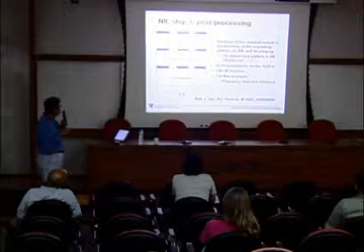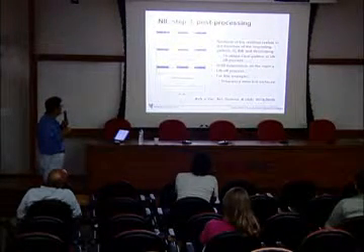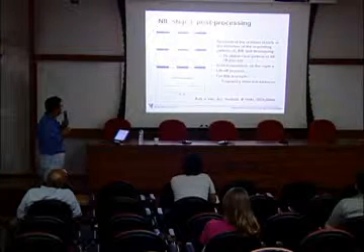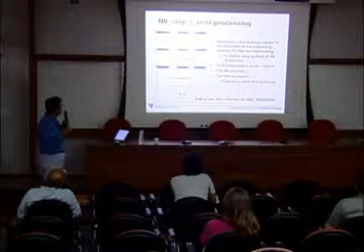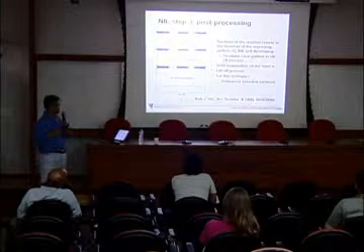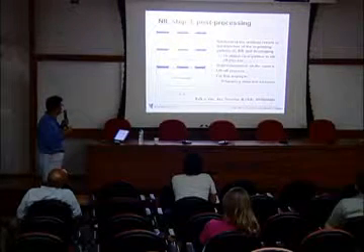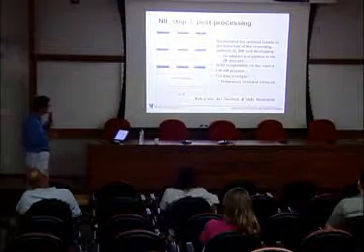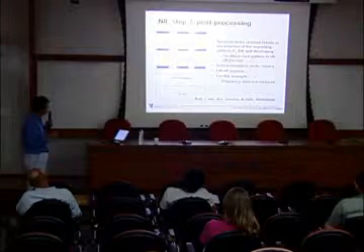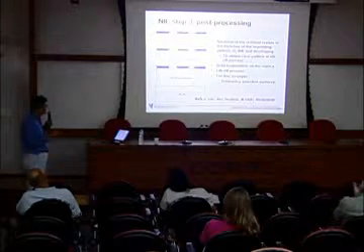So we have 2 layers of polymer, and then with the pressure and heating, those materials will be moved, transported. Then we have some of the debris out there. With the oxygen plasma, we can clean up the surface, and then we can coat a gold material on top by physical vapor deposition, and then we can remove all other polymers in solvent.